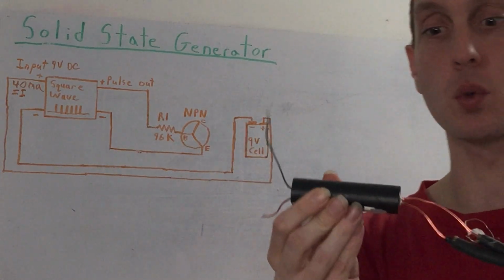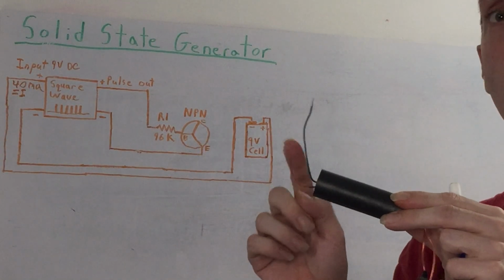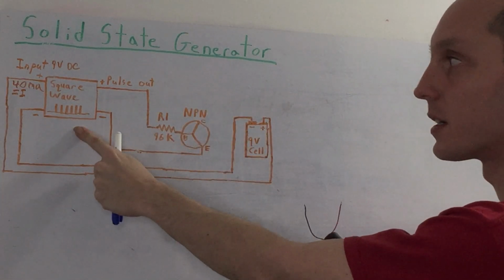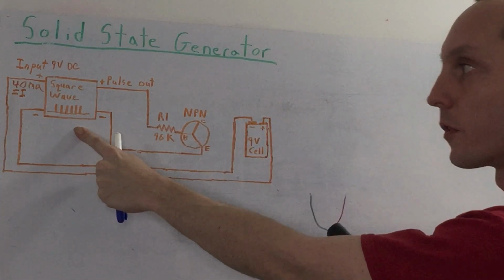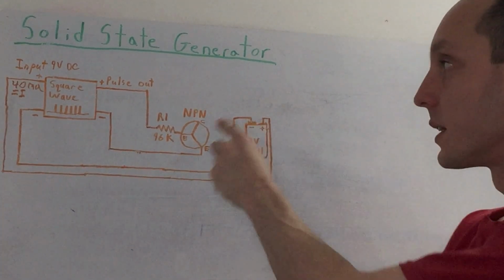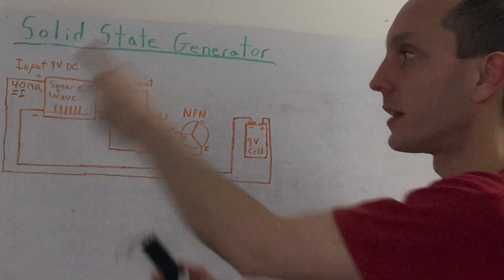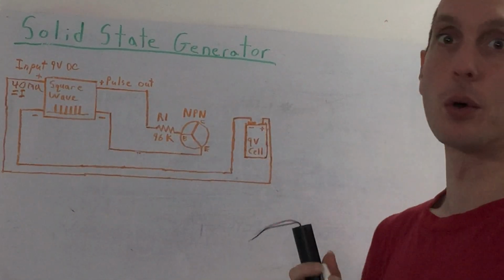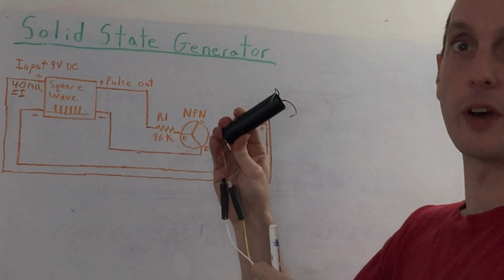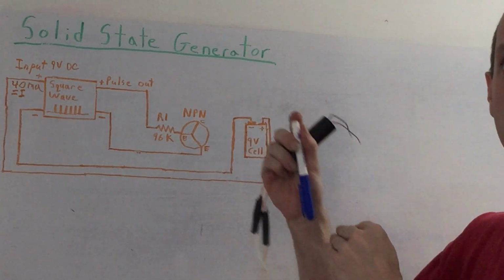So the way around this, whether it's an ionizer module or one of these, is to pulse the input with the help of this at a very low duty cycle, because this is how we can limit the current to just a few milliamps. In another video, I measured using this method and it was getting 45 mA. That's with the generator and the pulse controller, which means I was limiting the whole generator using only 5 mA, and I was getting 150,000 volts. So this is a great deal, and this is the idea.